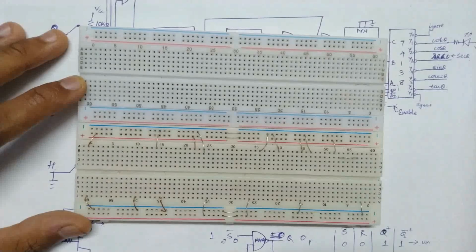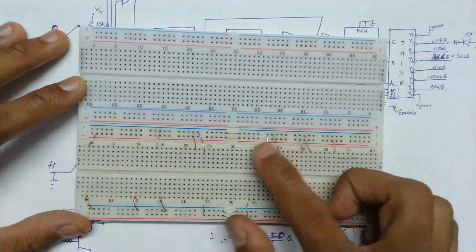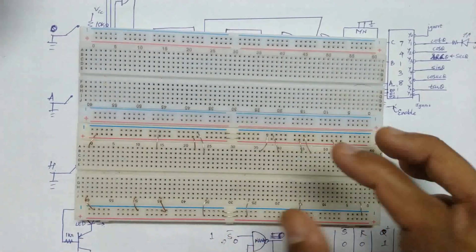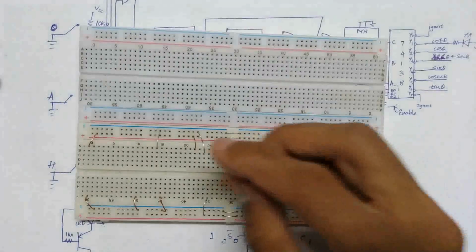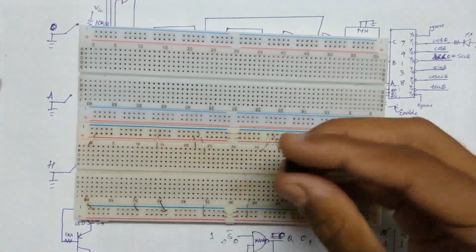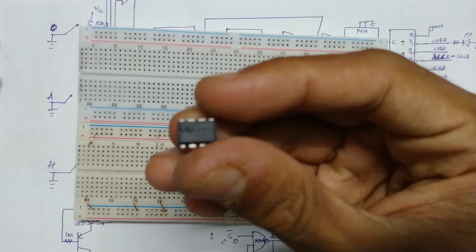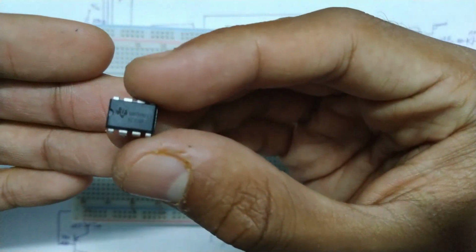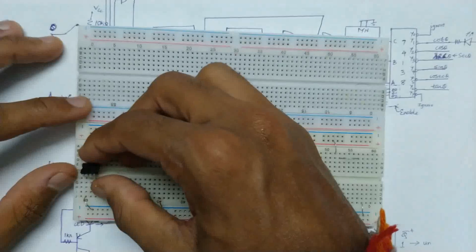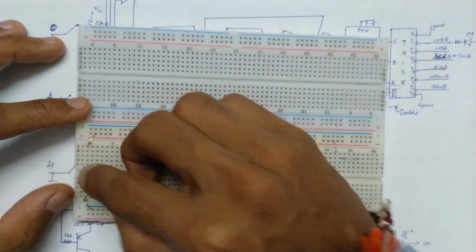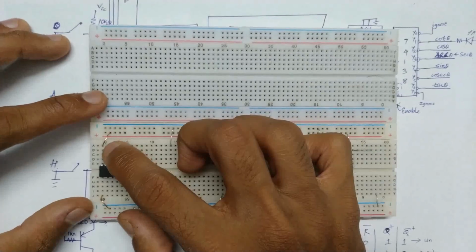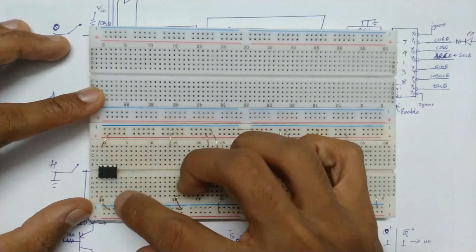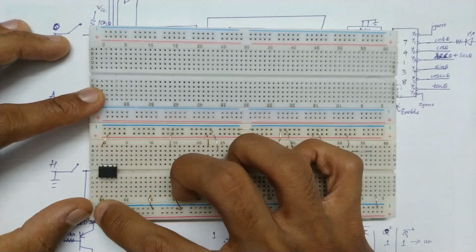I tried to rig parts of this circuit earlier, so there are some of these wires connected over here to the VCC and GND rails. So first off, in order to access the 555 timer's S bar R bar latch, we need a 555 timer IC. This is the NE555 timer, so I'll connect it over here in the breadboard. As you can see, pin 8, that is VCC, is connected to the positive rail, and the GND, that is pin 1, is connected to the negative rail via these copper wires.